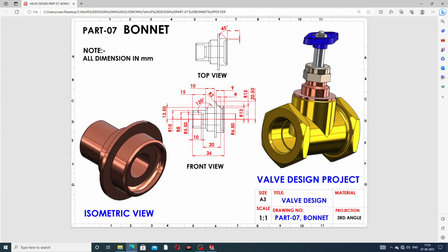Then all the geometry of the half part is drawn here. Then this axis of revolution is drawn here, and this length is 20.5 millimeter, and this is 15 millimeter, and this is 13 millimeter, and this is 6.5 millimeter. Okay, one by one is drawn here.